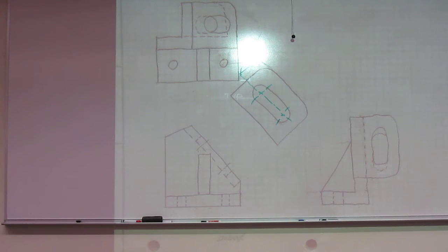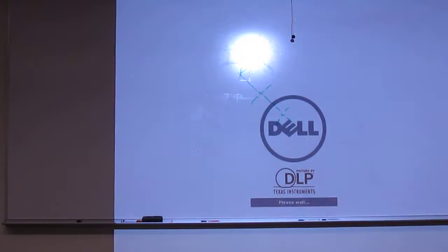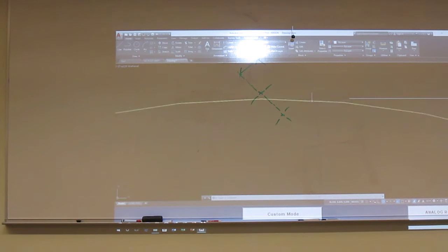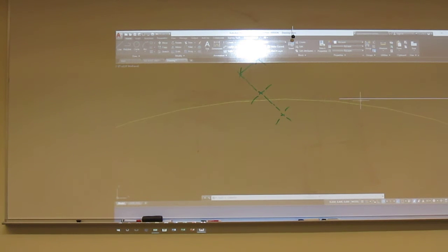I did kind of throw one out here because I did want to display it. I threw it on my screen, so let me switch to this real quick. So here's a case where I've got one, and see, on the computer it looks like that. I'll tell you right now, when I print that, I will not see that gap. So the best way to handle it is just grab your dimension. You do have grips right here. Now I'm just going to grab that grip and come back, and I just estimate where it's at. Let your puller kick in and I move that grip out.